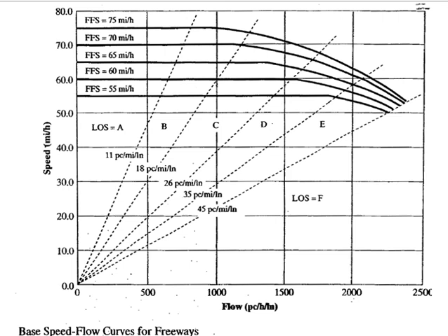Clear or not? I'm just giving you the concept. We haven't done any examples here. We will do them later. So you use the densities of each level of service which are given in the manual, and you take them as the slope and you plot these lines, and wherever these lines are going, you know this is the level of service. Okay, clear?